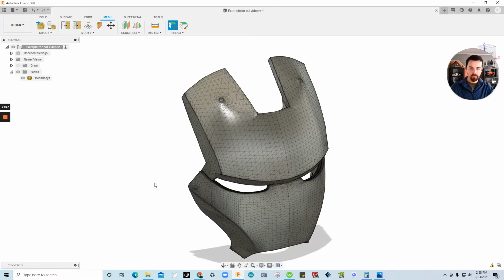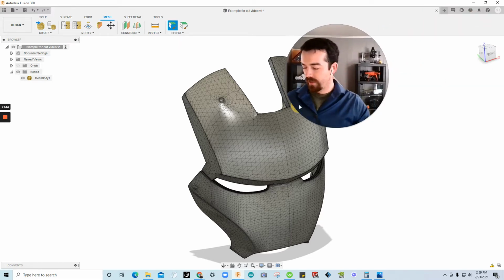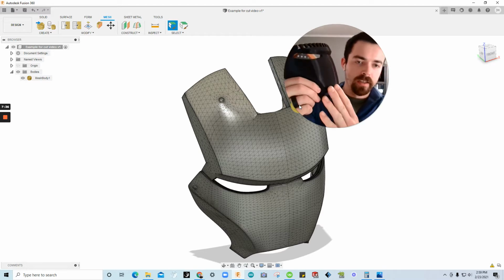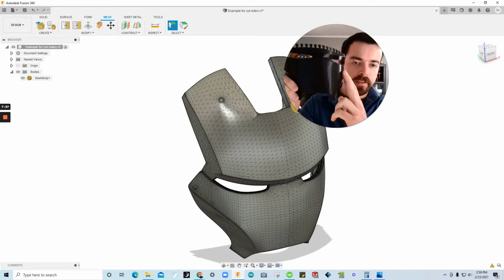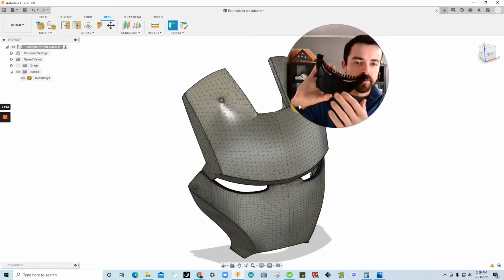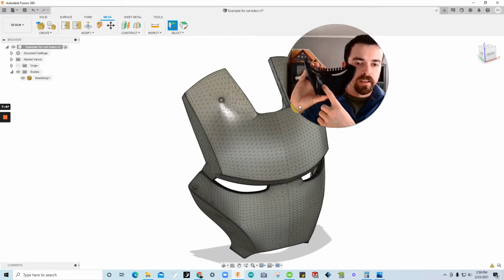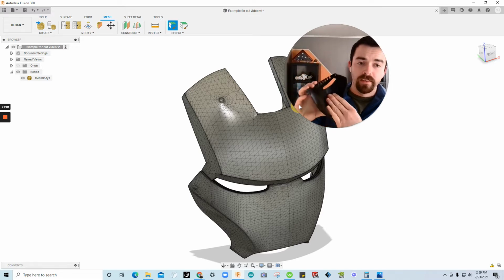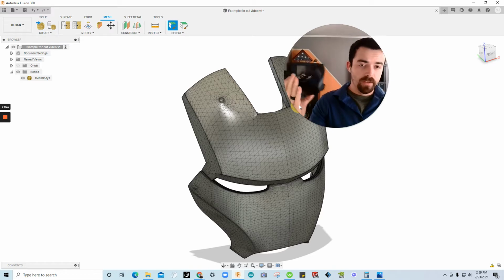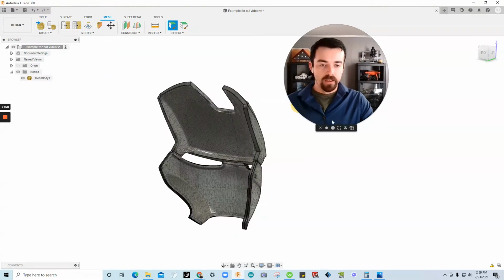So we go in. You do need to decide where you want, let me push escape here. You need to decide where you want the least quality of the print. And as you can see from this print that I did last night, high quality on the front because that's the visible edges, visible side, and then less quality on the back. If you can see the triangulation there, it's shining. It's kind of nice, and then large. There's almost no difference, but no one's going to see that, and that's where I would like to, if I was having to choose, like right now, that's where I'd like to reduce the quality.